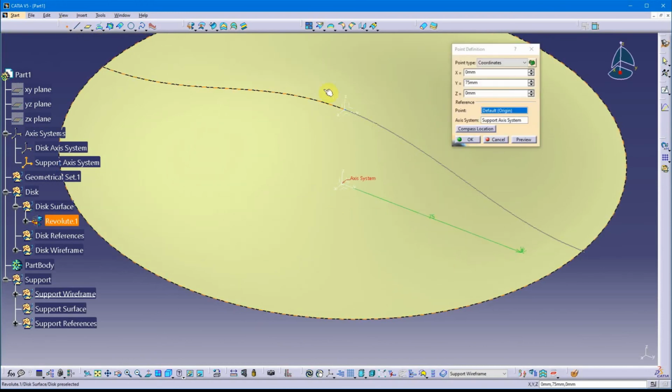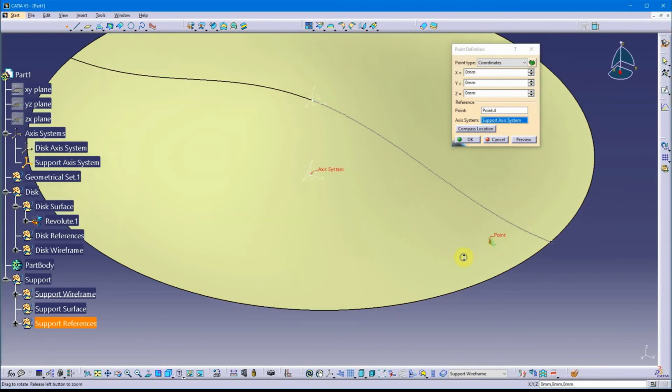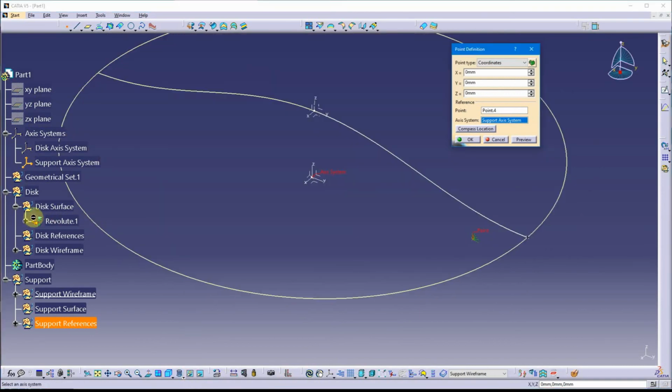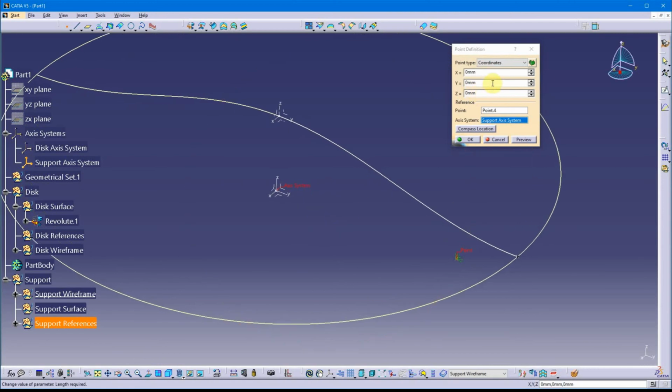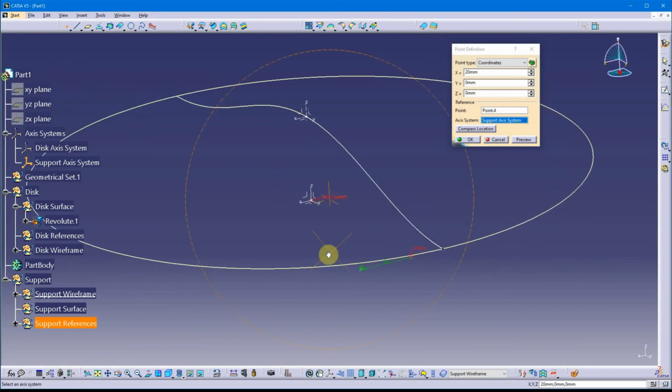So I'm going to double tap the point tool, just for reference, change that back to 0. Now my origin point will be the point that I created before. I want to change my display to wireframe. You can also hide this surface if you wanted to get that out of the way. And in the X direction, let's go with 20. Sorry, X direction, not Y. I'm going to go with 20 millimeters. See it coming out 20.